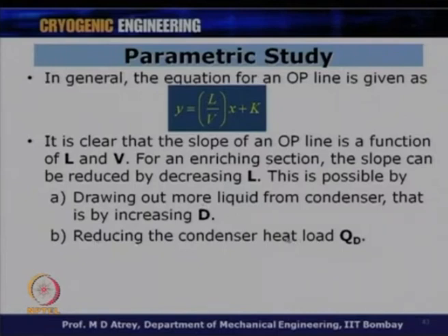That means I have less cooling effect available. So, whatever vapor comes on the top, I do not have the cooling effect available, I have got less cooling effect, and therefore, depending on Q_D, depending on the available cooling effect, 300 kilowatt, 400 kilowatt, I will decrease the overall condensate only. That means the value of L will decrease.